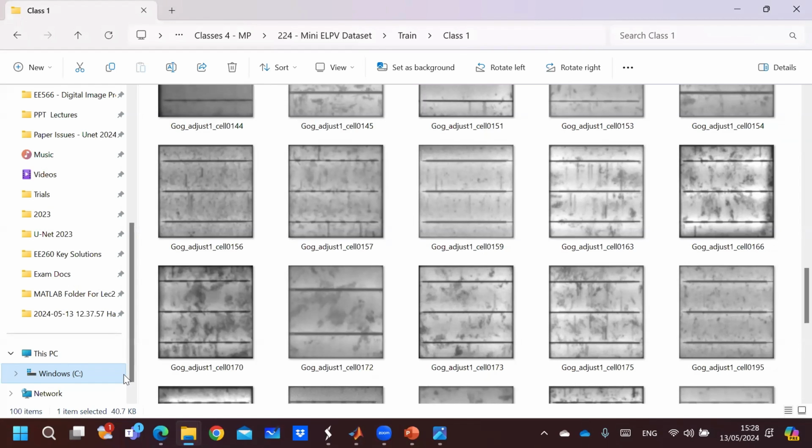In PV cells, just a small background for you, when you apply sunlight to the PV panel, the cells will convert the light into electrical current. Now, if you apply the opposite, if you apply an electrical current to the cell, it will shine. Now, you can take very accurate, specialized cameras, usually in a dark environment, to see what problems may be inside the cells.